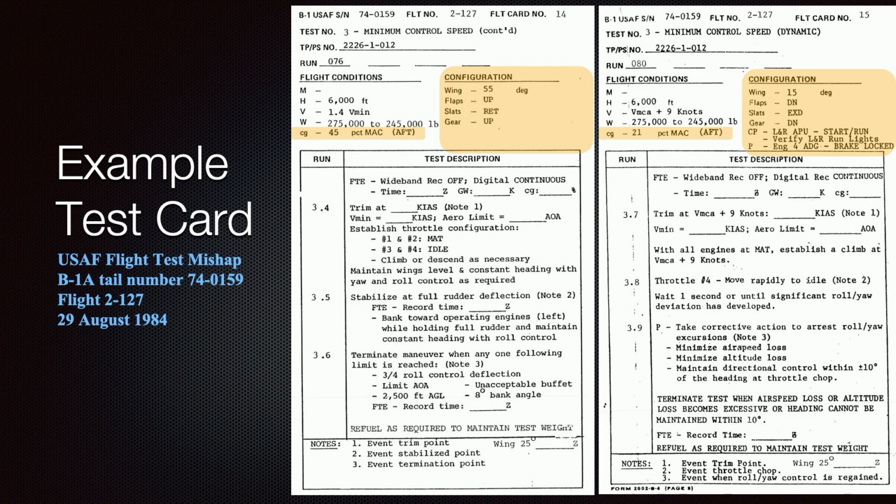It is a basic standard of aircrew professionalism to have checklist discipline. The flight test community's emphasis on following the test card and not doing things ad hoc is an extension of professional aircrew's emphasis on checklist discipline. The belief in the desirability of checklist discipline is based on the assumption that the checklist contains the best, thoroughly reviewed, and formally approved procedures. In the case of the B-1A mishap, the lack of specific order of configuration changes between test point 14 and test point 15 meant that operating in full accordance with the test card actually had a catastrophic consequence.